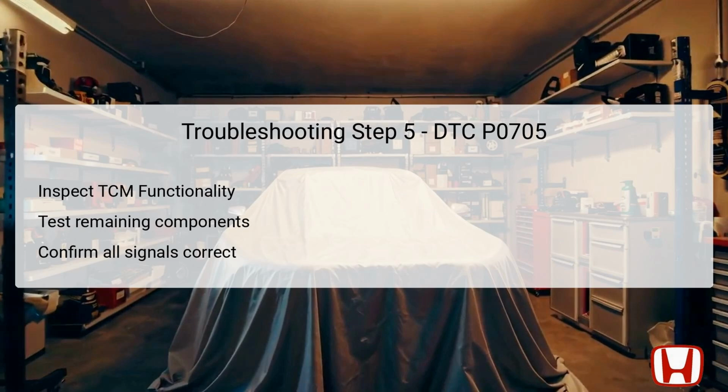If this module fails to perform, even though the input signals are within normal ranges, it may require recalibration or replacement. Addressing TCM failures can restore normal operation and clear the DTC. Ensuring thorough checks of all related components before concluding TCM as faulty will streamline the repair process.